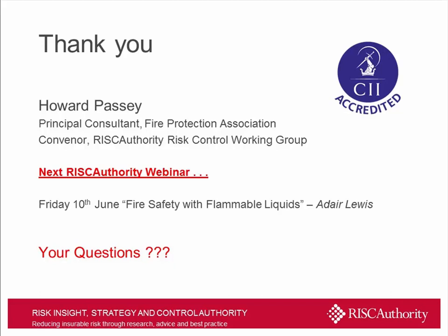However, there is additional guidance within the Joint Code which is designed to ensure that where timber frame is used, the potential for fire is minimised, and should a fire start, there are more effective mitigations in place than you might look for in a building constructed of masonry.